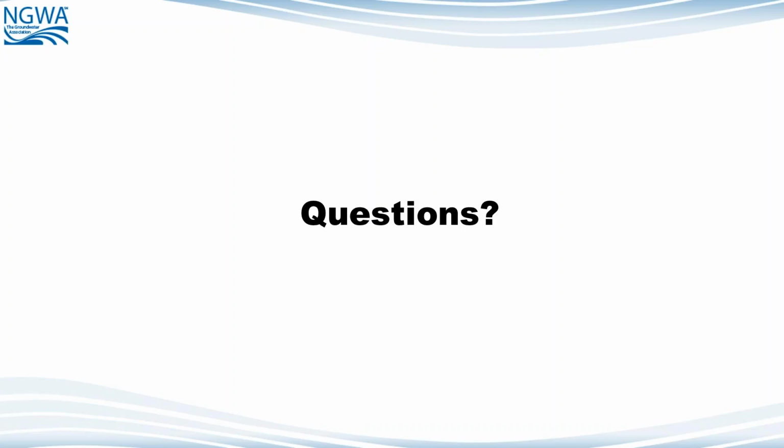Well, I'll first address the pH adjustment. There are two kinds of materials that are used to raise the pH of water. One is calcium carbonate. That's what a calcite filter is. It's granular limestone. And what happens is the water will go through the limestone. It'll tend to dissolve some of the limestone, which automatically raises the pH.